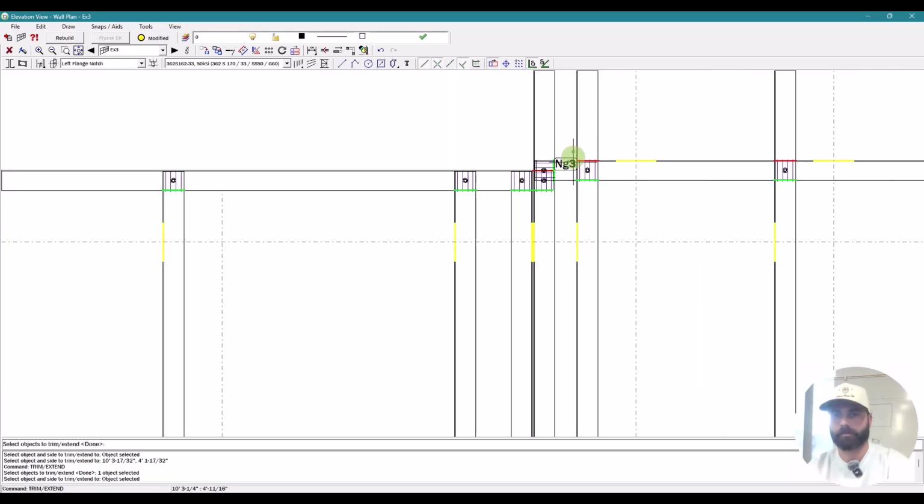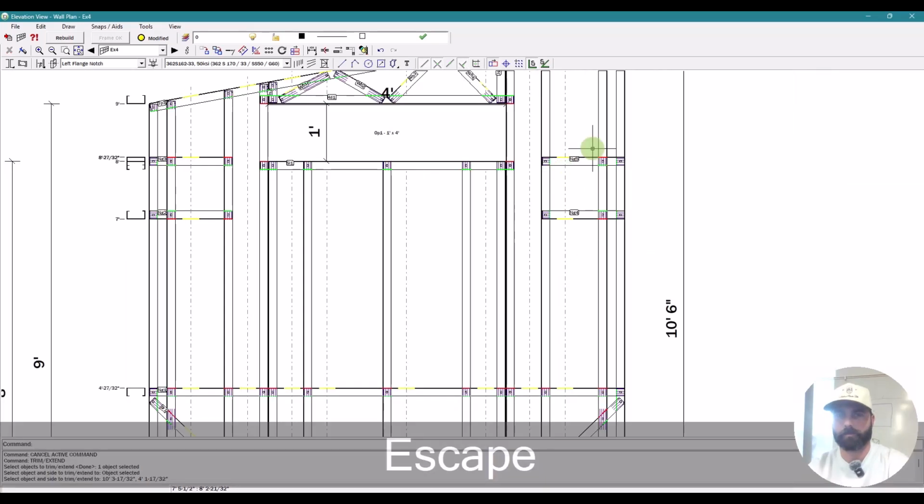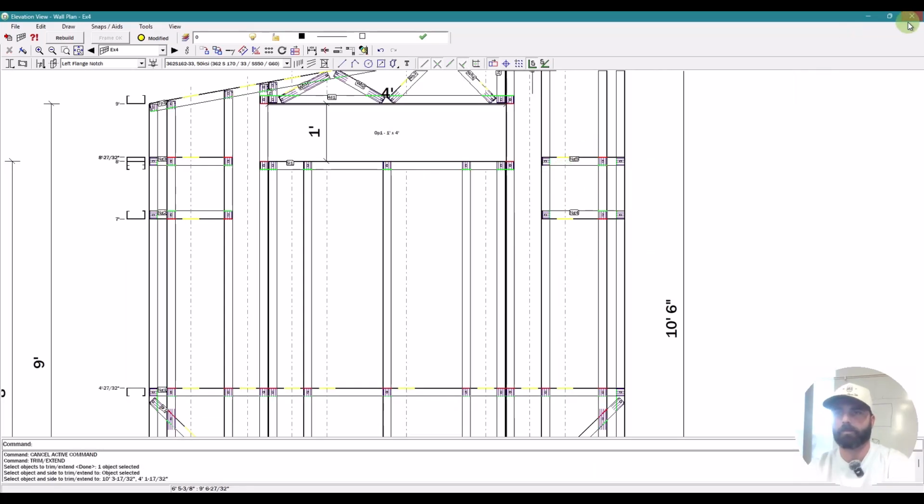Great question. What's most important is understanding, as things are coming out for production when you export it, knowing what the length of stud is. As it's coming out of the machine, it'll start with stud 1, bottom plate, then the bracing, then the nogging, then the second brace, and then the top track.